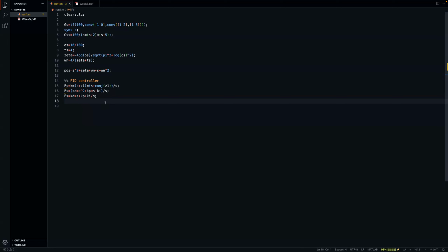But since we are going to use a pole zero cancellation here, I am going to drop these two for now, and I'm going to use this representation. Because I have to, because I'm going to choose one of the zeros of the controller. So when we talk about pole zero cancellation, the thing is that our controller structure does not allow us to get rid of or cancel any zero of the system, because our pole is fixed at the origin.